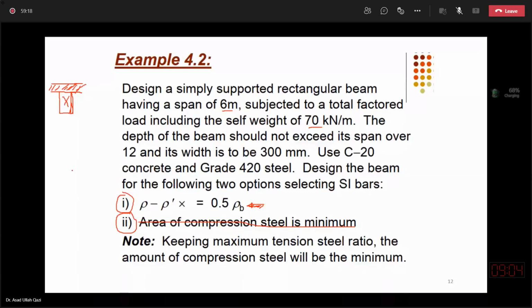It also carries some weight, and that can also be calculated by multiplying the cross-sectional area by the density of concrete. I may call it rho d, which is 2400 kg per meter cube, and it will then give me the answer in kg per meter.